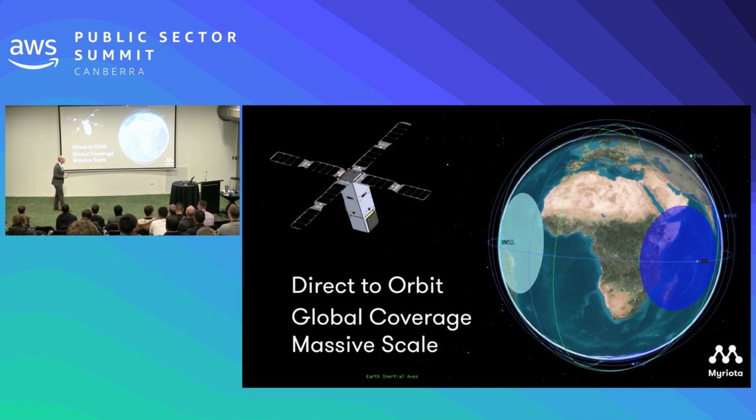So to start with, we're talking about devices where we're aiming to maximize battery life. So that means our transmitters are effectively whispering. And combining that with the fact that they're not talking to a base station that might be kilometres away, but they're actually communicating with a spacecraft that could be 2,500 kilometres away when it's out on the horizon, and the closest it's going to get to the device is 600 k's away when it's directly above. It's hurtling through the sky at 7.5 kilometres per second. So all of these things do quite some interesting stuff to the radio channel.